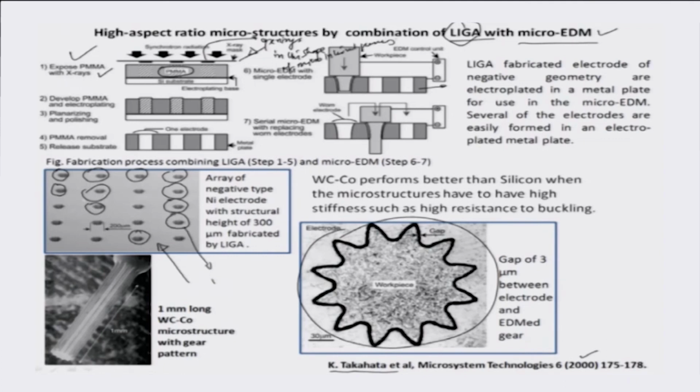These are internal gearings, as can be illustrated. Now if you look at the printing resolution of these gears, the internal gearings are of a diameter close to 200 microns, and they are placed away from each other by about 1 millimeter or so.